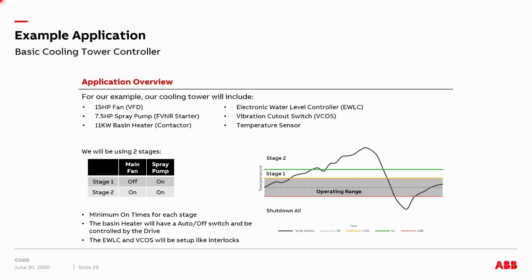I'm going to have 2 different stages. In stage 1, I'm going to have the fan off, but I'm going to be running the spray pump to run water through the fill. And then I'm going to expand on that in stage 2, kicking on the fan while running water through the fill at the same time to get some of that cooling that we require there.